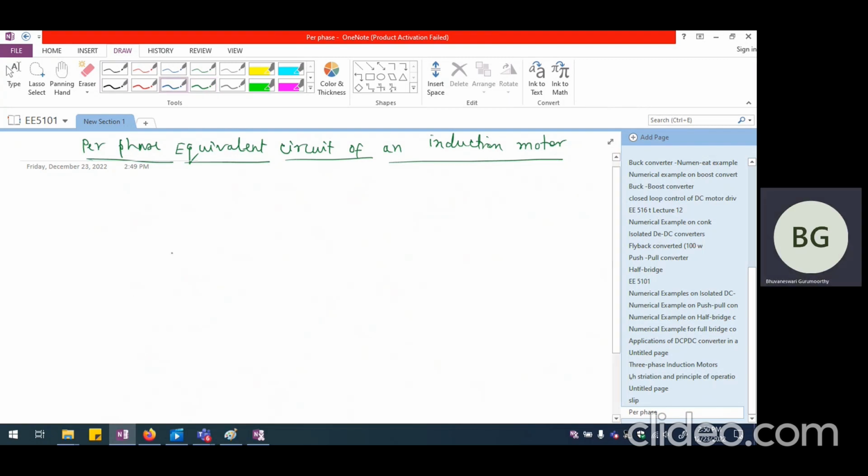So what we saw in the case of the three-phase induction motor, even one-phase cases, if this is my stator winding, A-phase winding, for example, and I am applying VA as the voltage for the A-phase winding, this is going to establish a revolving magnetic field. And if this is the A-phase winding of the rotor, it is going to have an induced EMF.